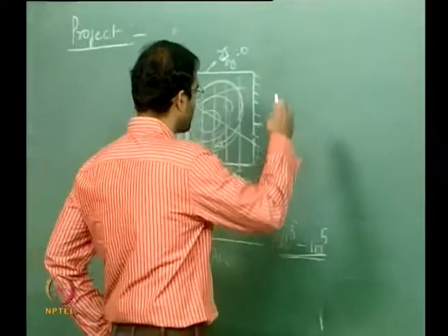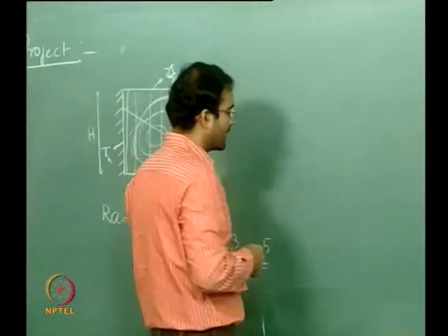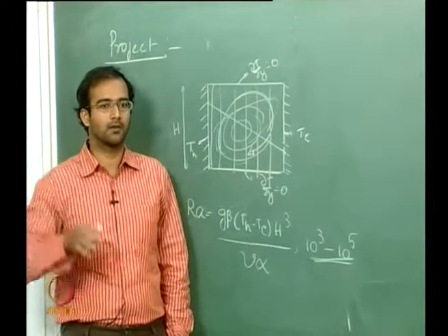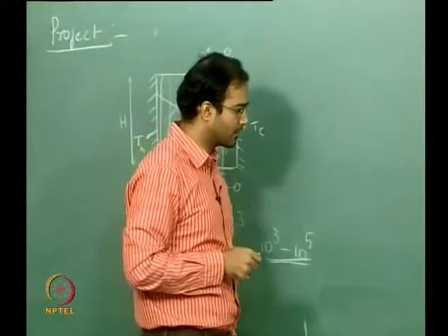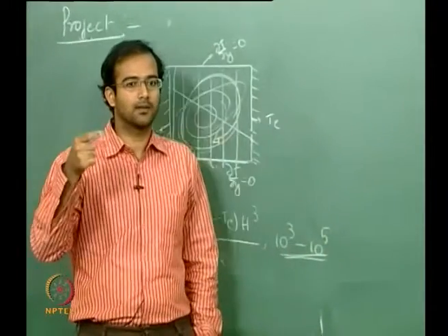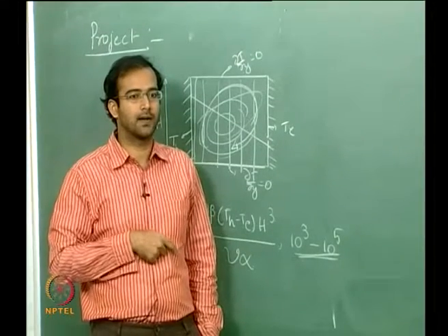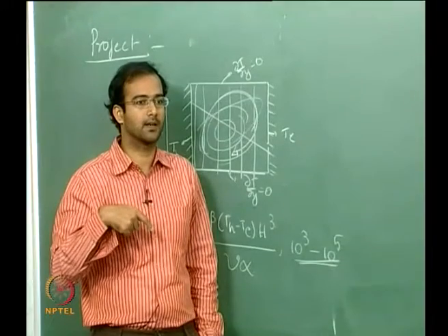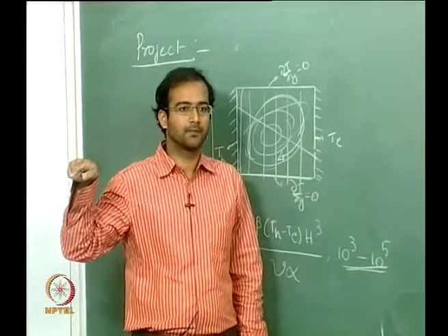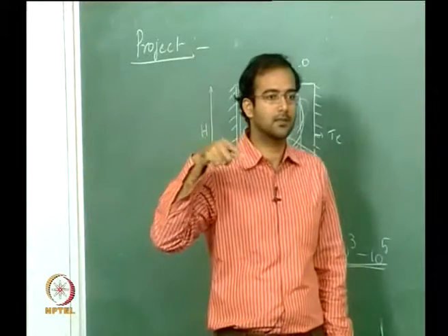So just to give you an overview of how the equations look for natural convection. If you introduce the stream function, the advantage is that continuity is automatically satisfied, so you don't have to solve the continuity equation. Now you can eliminate the two momentum equations by, for example, differentiating the x momentum with respect to y and the y momentum with respect to x, and subtracting the two. Therefore you eliminate the pressure gradients and finally get a single equation devoid of pressure. So you have one variable less to solve, and the number of equations also comes down.